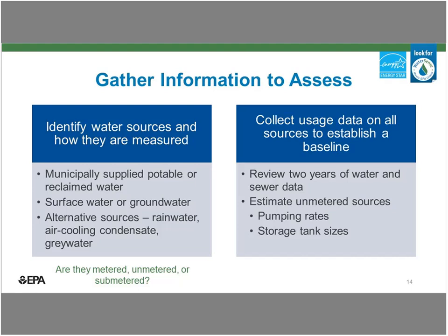Sometimes you can do that with just getting the information about the pump that's used to pull it out of that source. And then also if you're doing any rainwater collection or doing any recycled water within your facility, those are some other sources that you need to get a handle on and see how much is actually being used there. And you basically want to do that by collecting this data on, usually we recommend about 2 years of water and sewer data. A lot of times people in the facilities management office or department don't get the water bills. It often goes to the accounting department or somewhere in the administration.